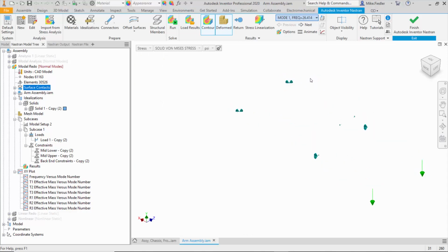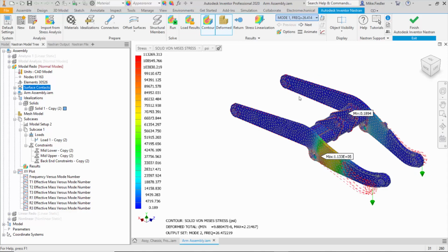I hadn't intended to necessarily show modal analysis whenever I was first envisioning this particular webinar, but it's good that the model ended up doing this so that I could show that modal analysis is a great way to figure out, potentially, where there are parts that, if you have a large assembly, you may not have initially noticed were unconnected. I wasn't the one that constructed this original geometry, or if I were, I certainly would have been aware of that coming into the model setup.